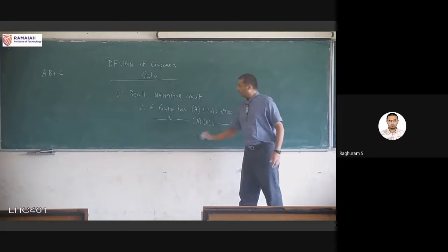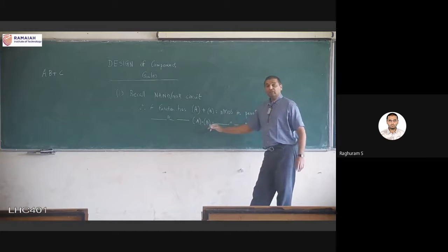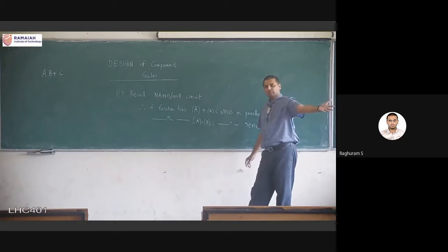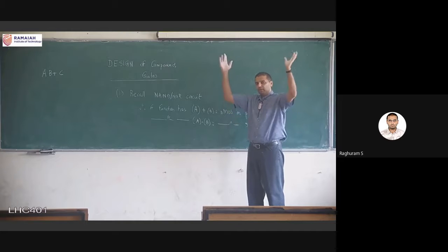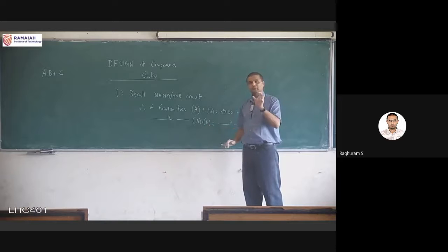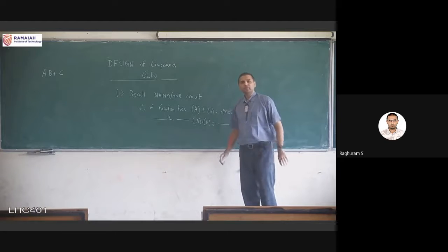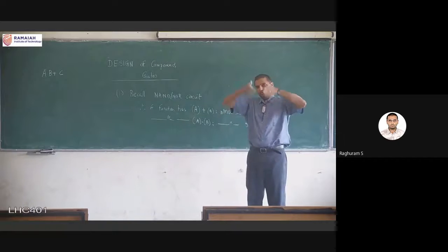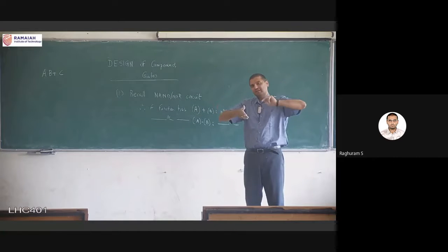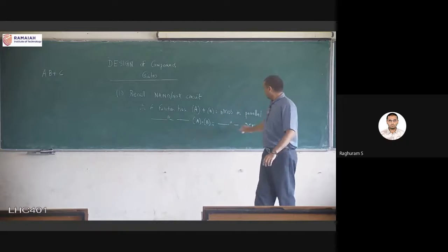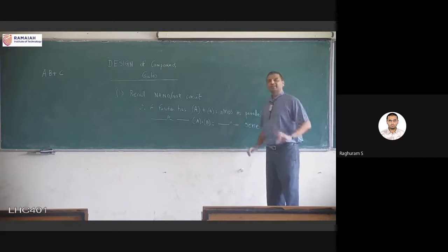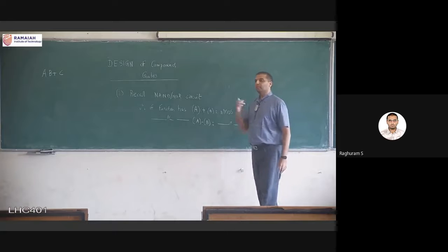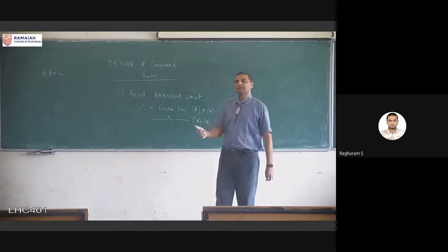Similarly, if I have two transistors, two terms in my logic function can be anything, but I will build them term by term. By seeing the smaller AND or OR terms, we will slowly go from the bottom level to the top level. If there are two terms being ANDed, you remember the two input NAND gate, the two NMOS transistors were in series, so it was A and B. So here also I have to put those two NMOS transistors in series. This is the first thing that will help me design my pull down network.